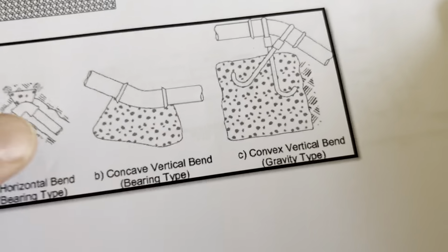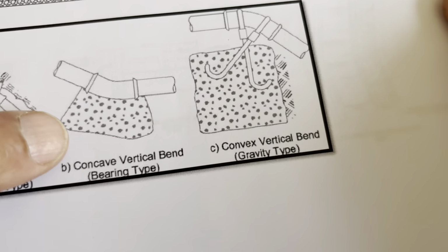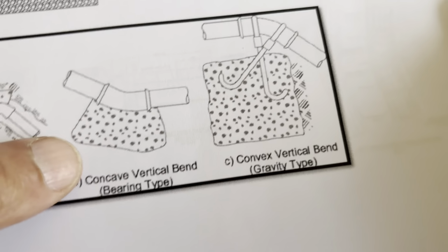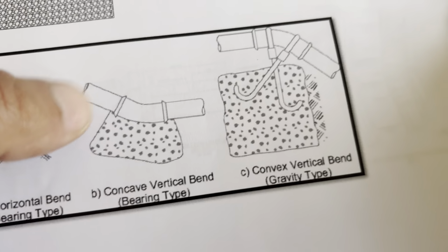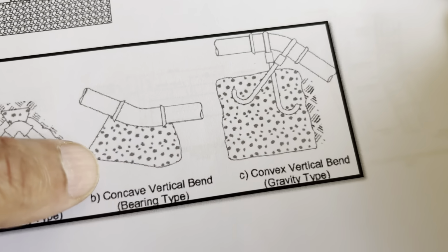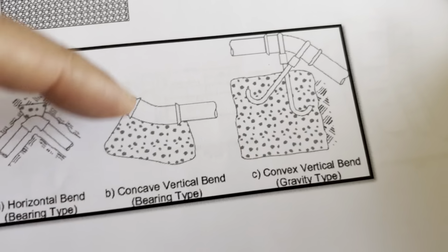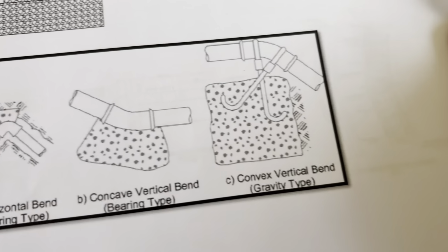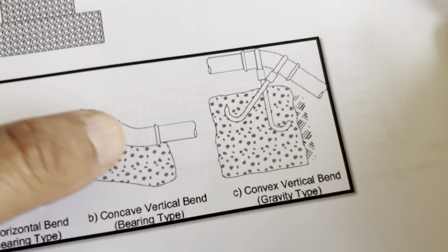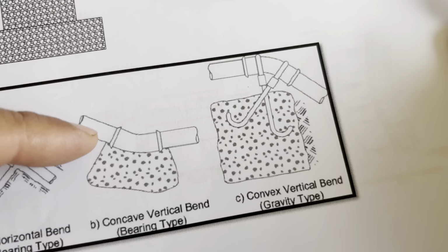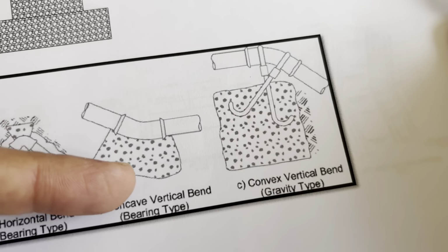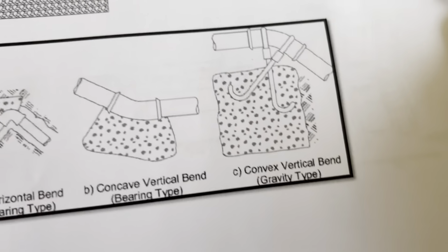And same here, it is something like a vertical bend that causes lifting up the pipe, and we need to have something heavy to take that piping system down, and we need to anchor it to the piping system. So changing the direction of the fluid here is just lifting the pipe, but this gravity system pushes it down.